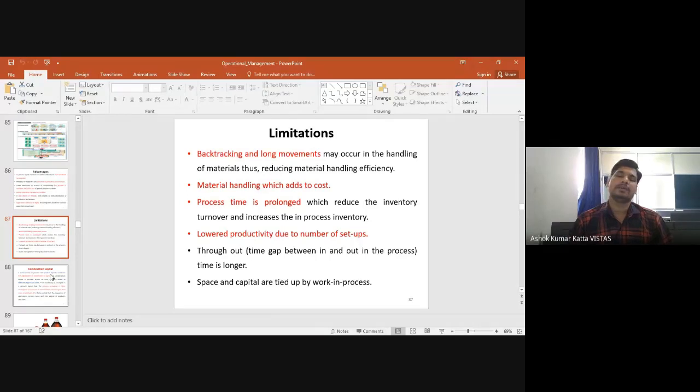One machinery is performing more than two different kinds of activities, so more time will be taken for manufacturing of the product, because we need to manually transfer the product from one machinery to another, from activity A to activity B, then another machinery, activity C to activity D. Sometimes manual help is required, or sometimes we require additional machinery support to transfer the product. Many things can be seen as limitations of the process layout.